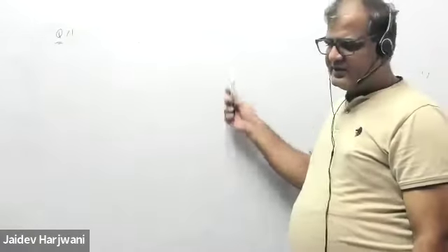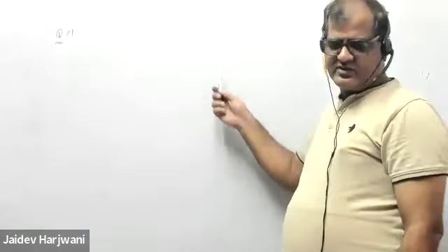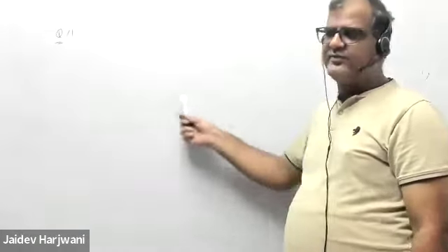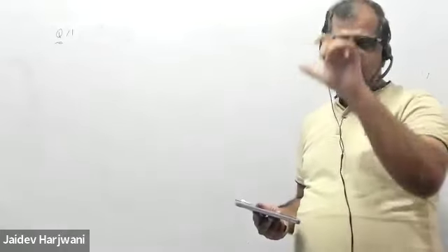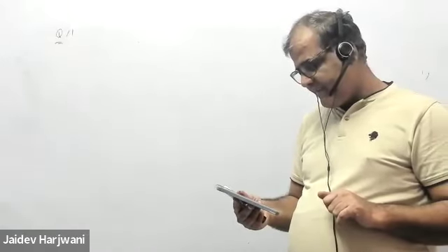Then how will the series look? Series cannot be there, na? Here current cannot go series to series because this current is going through shunt only. Sir, RL is a shunt here. Huh? RL is shunt. So whatever voltage is across RL, that is getting divided in series, na? That is the shunt series. Okay, I'll send some videos on different types of feedback, then you understand.